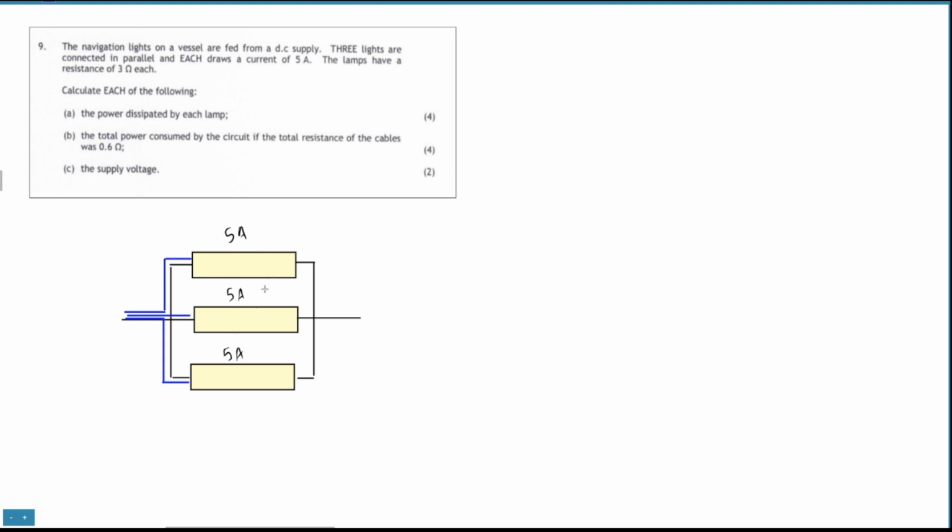The 5 amps are being supplied to each one, and then they're collecting again at the end. So they're all coming together again. So there's 15 amps going in, 15 amps coming out, but those amps are being evenly distributed between those 5 lamps. Normally this is a lot more difficult because the lamps or the components are different sizes, so we have to sit down and calculate them all. But like this, we don't have to. They're just all exactly the same. Makes for quite an easy calculation.